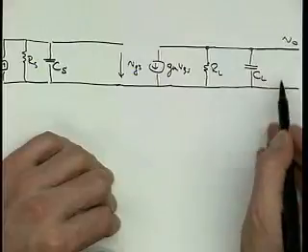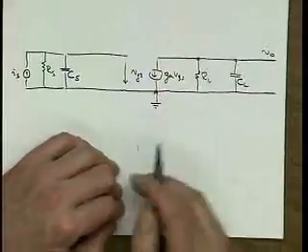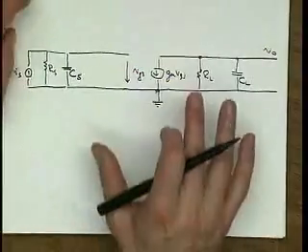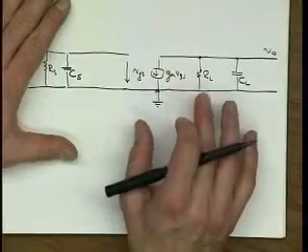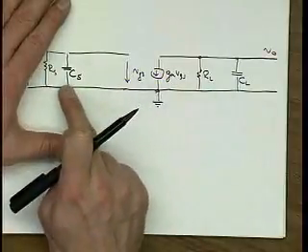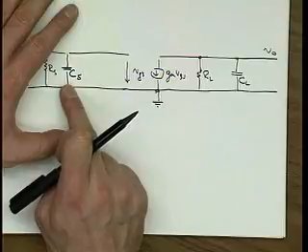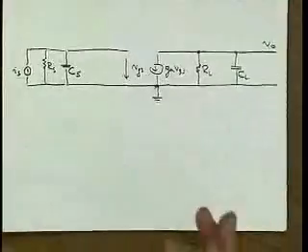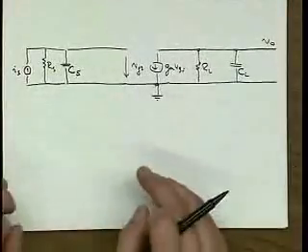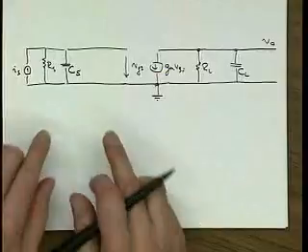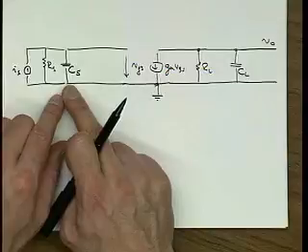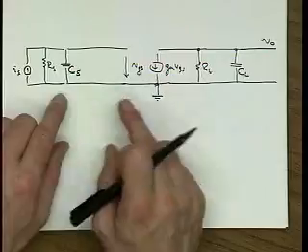And that's V out. Okay. All right. So now, of course, the transistor itself also has its own elements, like it has a CGS that is going to add to a CS here, and it has an R out that goes in parallel with RL. I kind of cooked this example so that you can verify that those contributions are negligible. The CGS is very small compared to CS, which I've deliberately chosen large at about 1 picofarad.